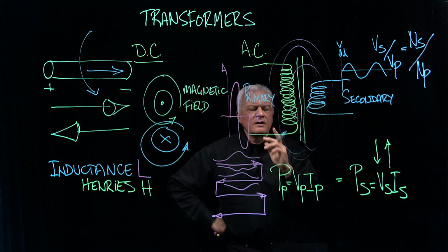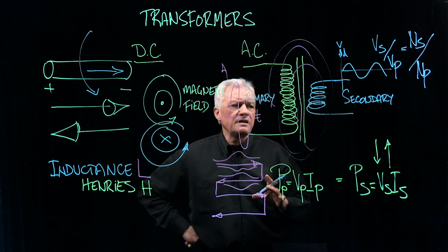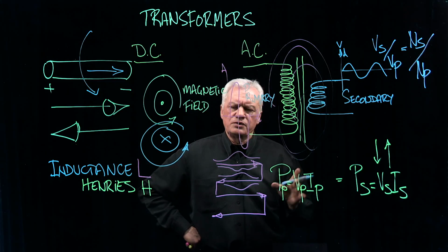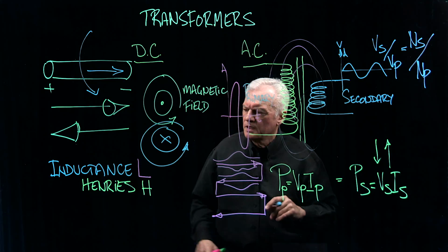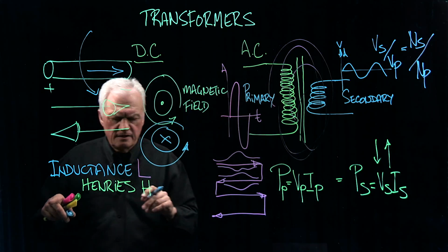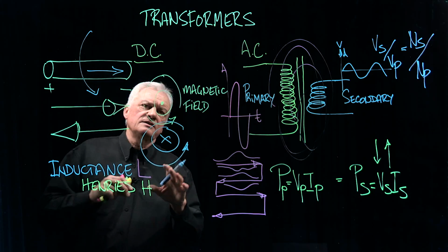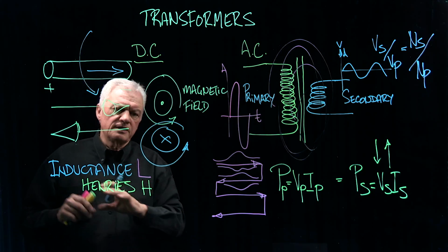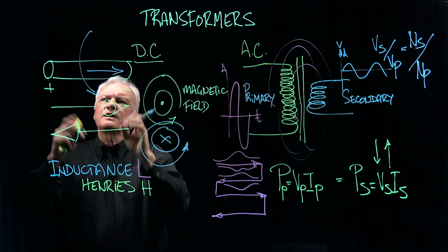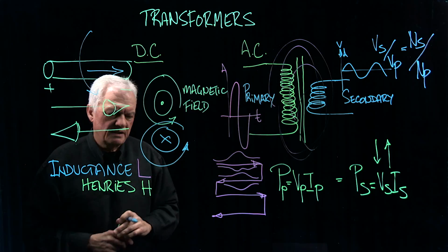Now, not always present to you in a data sheet, and we'll show you a data sheet in a minute, is the actual turns ratio that way. There's another way of determining turns ratio. If we go back to our inductance side here, the fact that I'm trying to create a magnetic field, this inductance causes a small problem in just how fast the charge can move. I can put the voltage there, but the charge can't move right away because it's somewhat pushing to create this magnetic field.